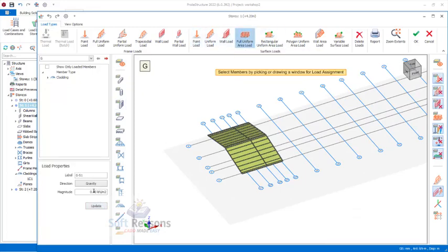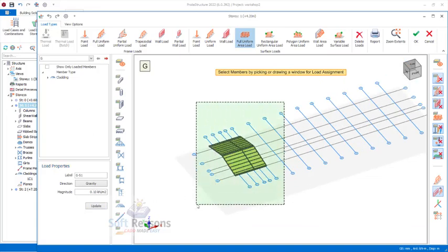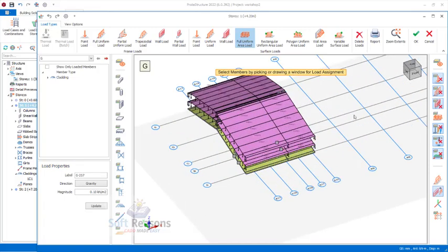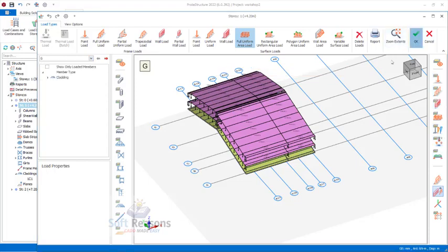We'll be using 0.1 as well for the dead load. Select all of that, so you can see the load is being placed successfully. In this one we'll only work with the dead load. It is double, so the first layer will serve as the dead load and the second layer we make serve as the live load right there. So click on the OK option.